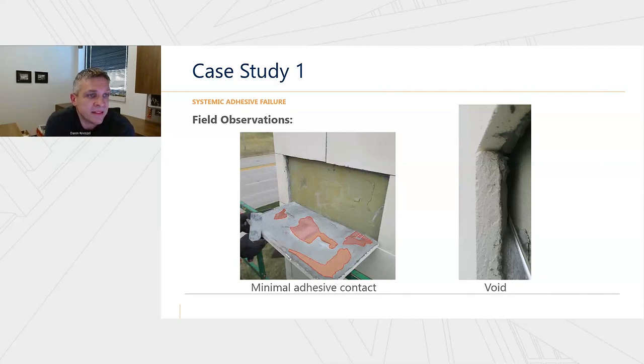In this case, the veneer manufacturer actually required within their written manufacturer's instructions that they achieve the squeeze out on the unit perimeters as well as a fully pointed system, so it did not permit for a dry stack system as was installed.